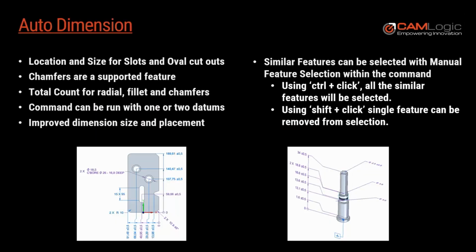We leverage the free viewer that comes with Solid Edge, and we use the model-based definition to communicate what is needed for an assembly or a part we're manufacturing. That free viewer allows anybody on the shop floor and the manufacturing team to see the assemblies or parts made by engineering, and see them in 3D with all the necessary PMI that are needed to manufacture that part.